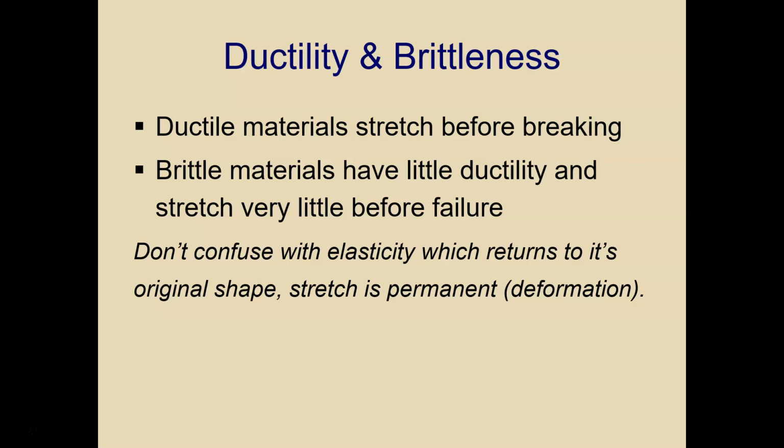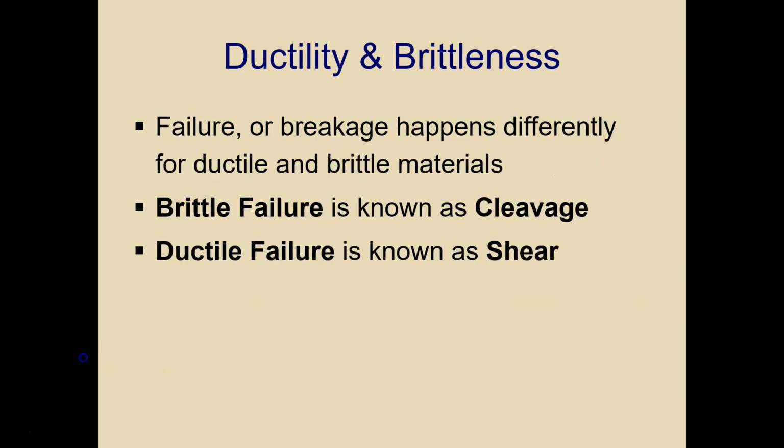Don't confuse this with elasticity, which returns to its original shape. The stretch is permanent deformation. Ductility and brittleness. Cleavage occurs in brittle materials, and ductile failure is known as shear. Remember those two terms and what they relate to. Cleavage to brittle, shear to ductile.